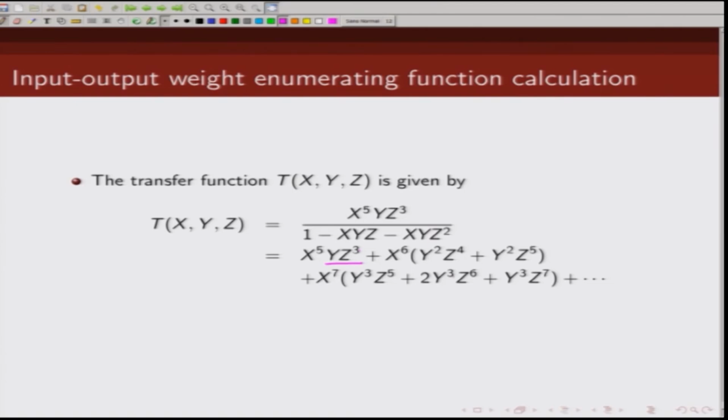Similarly, we had shown that there were 2 code words of weight 6. This completely specifies what those 2 code words were: one generated by message bit weight 2 with length 4, the other by message bit weight 2 with length 5. So, if we use the augmented state diagram to generate a transfer function, it gives us a lot more information.